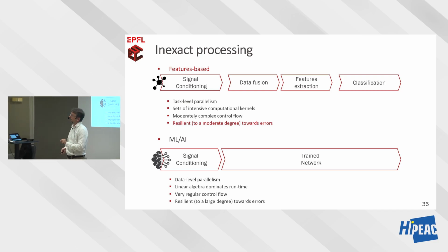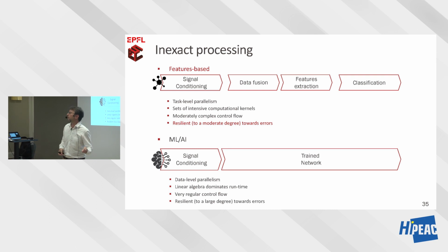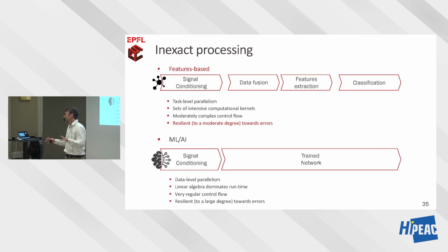The answer is they were implemented at the instruction set architecture level, which means that you need hardware support for that, but this is pretty minimal, because basically you need provisions for a +1 counter and little else. And at the software level, the software developer has to put these pragmas inside the code. We actually provided a library which hides this complexity from the end user, but still we didn't have real compiler support, and we instead used inline assembly for issuing these pragmas.